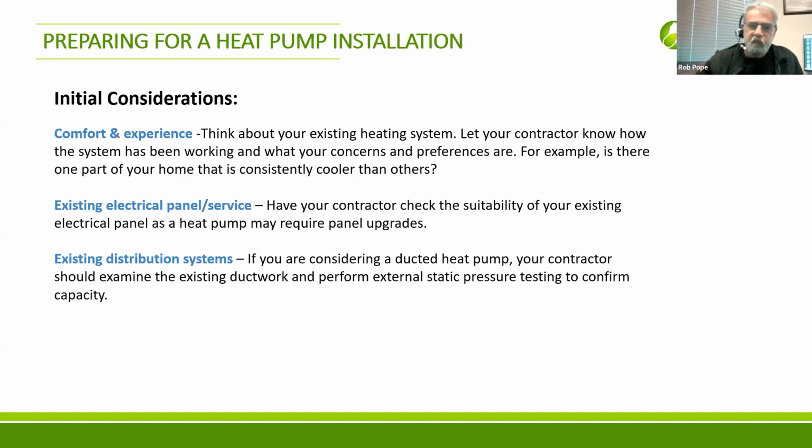Okay, so comfort and experience, electrical panel, existing distribution system. Again, in a retrofit, you don't want to assume that the ductwork is adequate. You want to make sure that it is. There are things you can do if it's not. Any good mechanical contractor or HVAC contractor will know what those things are. For example, you could put an extra return in on a wall that is common to the furnace room and the hallway, just to relieve some air. There's a few things you can do.